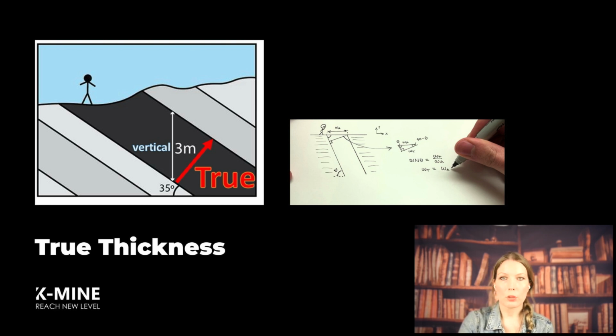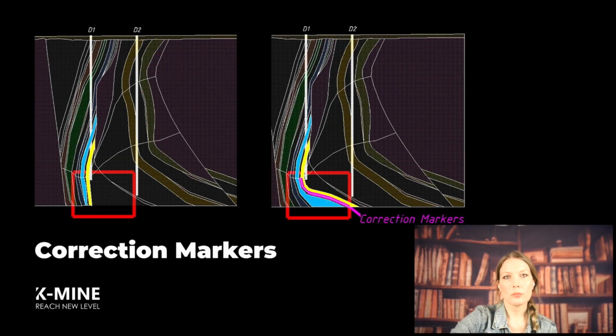Then the average is calculated, the upper and lower planes are constructed, and from the center of mass, 2 perpendiculars are drawn, and the arithmetic mean of these 2 perpendiculars is used as the true thickness, which is then assigned to each block in the model.